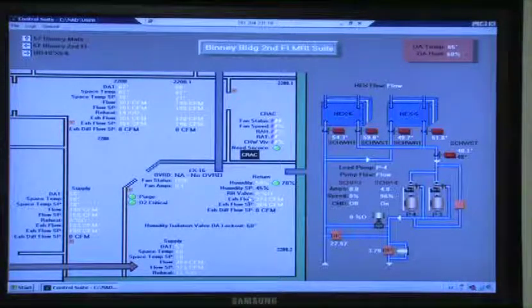Yep. Go ahead, Mike. Aren't you going to be concerned about having any condensate collecting in that line when you first start up, having moisture come down through that humidifier? Sounds like a question for a plumber. If it's isolated for summer and when we start to use it there's condensate in that line, you send that sitting liquid in that pipe downstream and you're pushing it through that humidifier. You don't want anything dropping out and getting any moisture in that room.